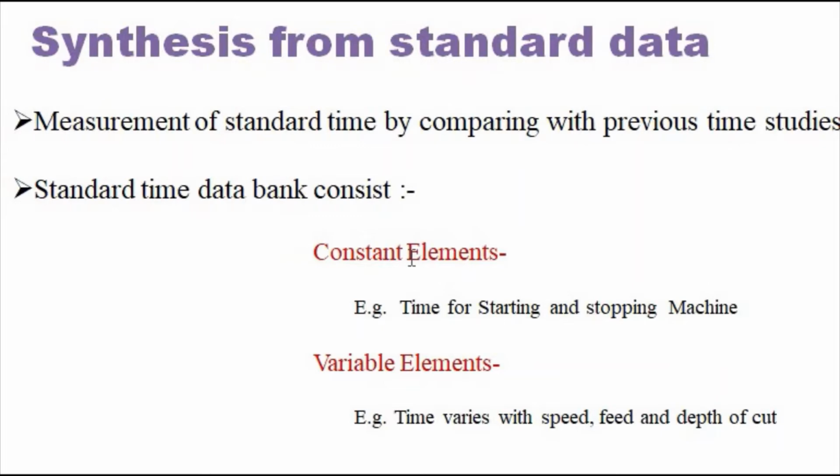Various other common elements are also considered, because while calculating the standard time, basically two different types of elements are there. These elements are classified into constant elements and variable elements. Constant elements are those elements which are repetitive, like the time for starting and stopping the machine.